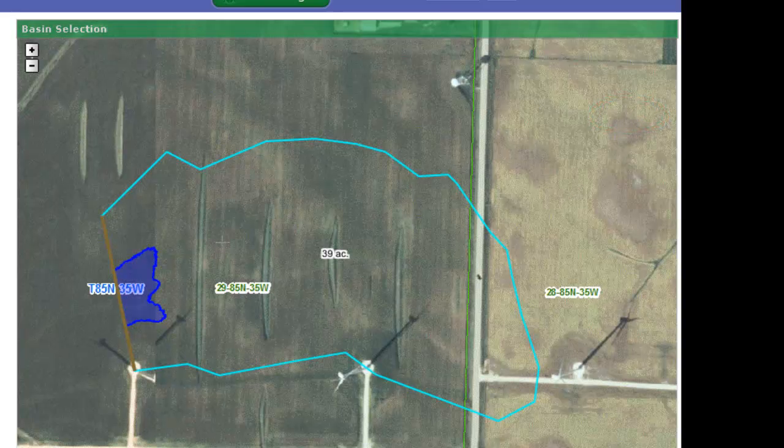I will then get my aerial photo that shows me the pool size for the water and sediment control basin that I chose. And so, as with all water and sediment control basins, there's no permanent water because there's a tile line at the bottom that drains the entire water and sediment control basin. So I don't have a permanent and temporary pool, I only have a temporary pool.